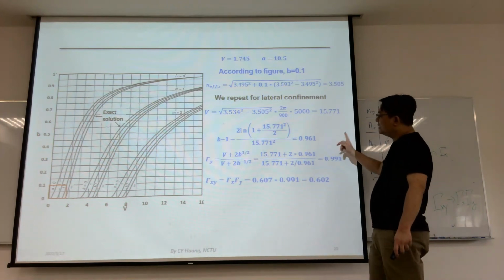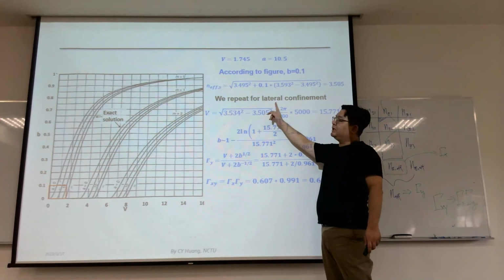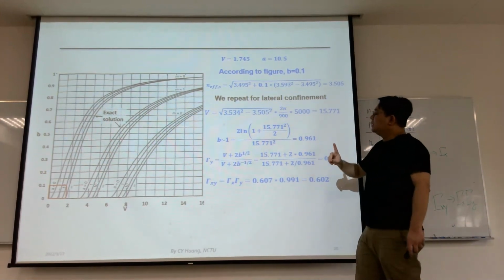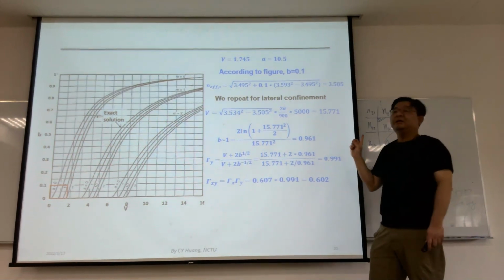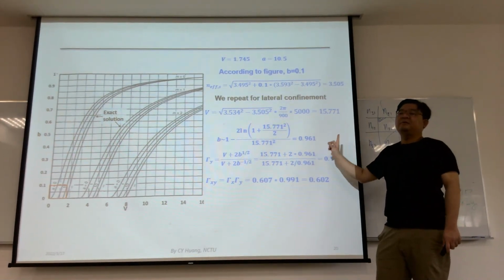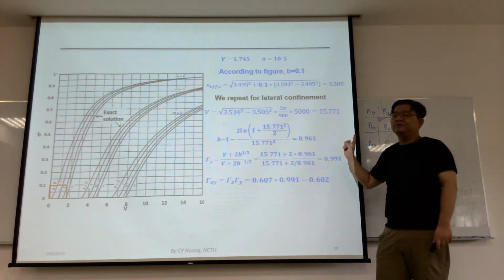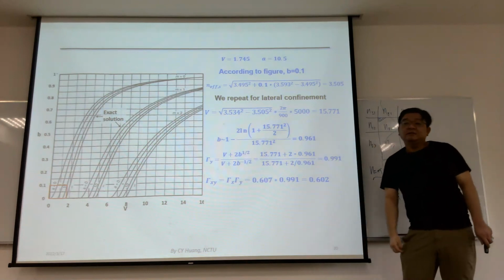According to the numbers, definitely you will get a smaller V, and a smaller gamma y. Your confinement factor will be sacrificed. With the sacrificed confinement factor, your threshold current will also be sacrificed.